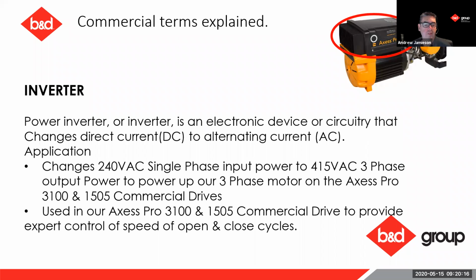It's basically a variable speed drive by the sheer fact that we can control the hertz coming through the supply, and we can speed up and slow down for bespoke operation, and we can also change the cycles individually. So especially when we're getting into commercial space, we need that ability to stop that slamming action at the fully open and fully closed, and we do that by having that soft start and fully adjustable speed.